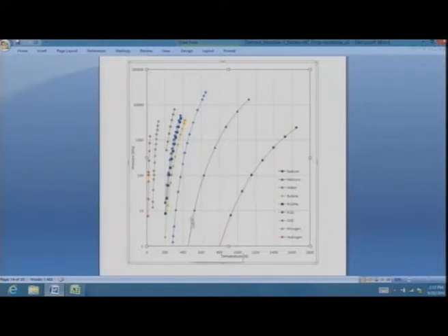But you can see that here now the temperatures have gone very high before we can even start thinking of mercury becoming a saturated liquid. So for instance, at 100 kilopascals, which is here, the saturation temperature of mercury is about 600 something Kelvin. It's a fairly high temperature before mercury will begin to boil. And on the right is sodium. And here you can see that at 100 kPa, sodium will melt at about something like 1150 Kelvin. Fairly high temperature when it melts, and after that it can boil or change phase at constant pressure.